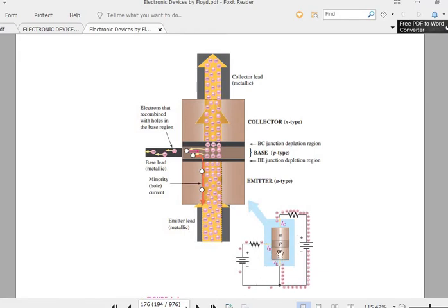Here this flow of the direction means electrons make this p-type semiconductor material, although here the majority carriers are the positive holes, but we are having the flow of electrons and this is a thin layer, so this causes the diffusion of the electrons to the base region because of this flow of the electrons.